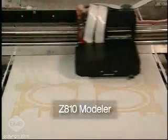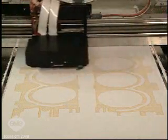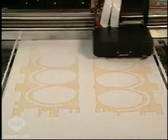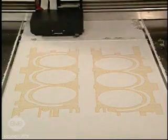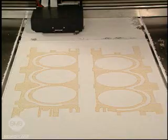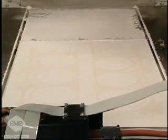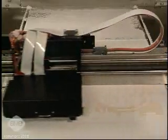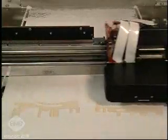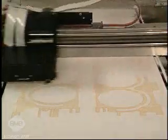The Z810 modeler is among the fastest rapid prototyping systems, having a building speed of 1 to 2 inches per hour. The Z810 modeler uses one of 2 powder material types to build models. The first combines starch and cellulose, and the second is plaster-based. Both materials can be subsequently infiltrated with wax or particular resins to enhance certain qualities.